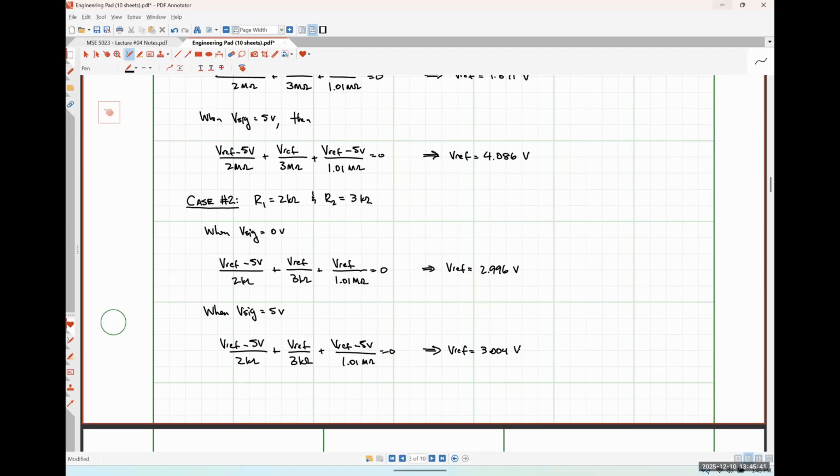So generally speaking, the sweet spot for resistor biasing an op amp is to use kilo ohm size resistors for practically everything. Okay. All right, that's enough out of me for today.